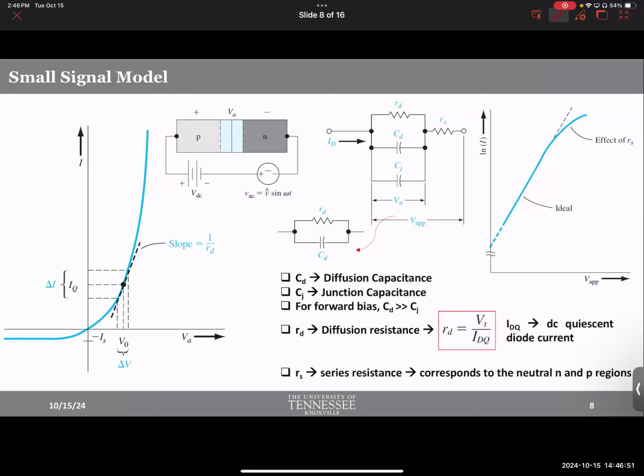All right. So you already know how the IV looks like. There is a turn-on point, there is a breakdown voltage and whatnot. We are just gonna cover this from the theoretical side very quickly because there is an actual practical aspect associated with it as well. So in electronics, we often try to make a conceptual model for any device that we encounter. It could be MOSFET, BJT, diode, or something more complicated. We try to represent the features of those devices using simple circuit components.